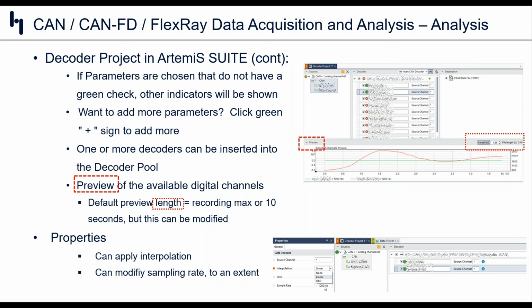So at 48 kilohertz, it just so happens that 48,000 divided by 48, which is a factor of 2, is 1,000 hertz. If it's 44.1, it'll be a little less than 1,000 hertz sampling rate. If you needed this to go higher, you can change this to 10 kilohertz. It'll max out though. It'll just oversample, upsample the data, maxed out at the data rate that was specified in the DBC file.